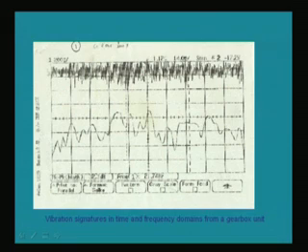Why are they happening? Why are these peaks coming in the signal? They are of our concern because if a particular frequency is coming high, like if we are measuring the human heartbeat, and we know what the frequency of the heartbeat should be, and we get the amplitude very high corresponding to that, we will be worrying what is happening to the heart. Similarly, in the machinery, we will have several machine components. Every machine component will have a unique frequency, and if a particular frequency has very high amplitude, then we will be worried about what is happening to that particular component.